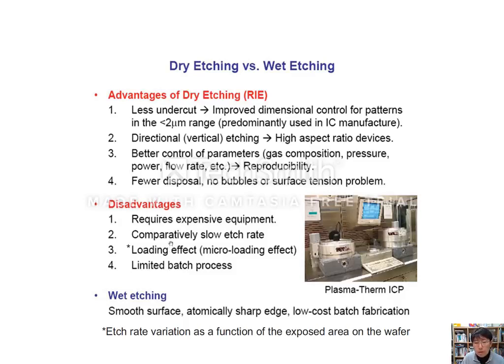Also, the etch rate is relatively slow, and there is more loading effect. What is the loading effect? It is the etch rate variation as a function of the exposed area on the wafer. We discussed loading effect a couple of slides ago in my presentation.